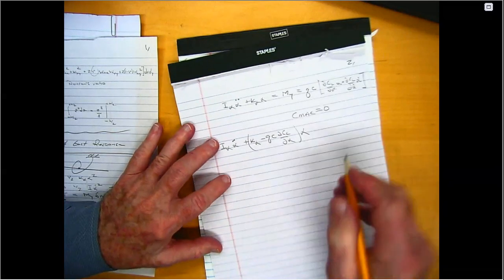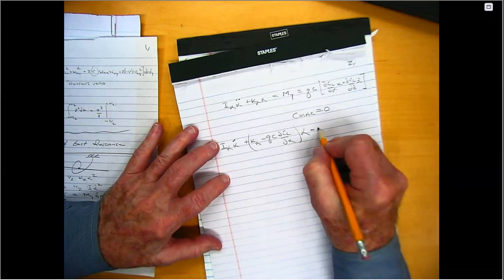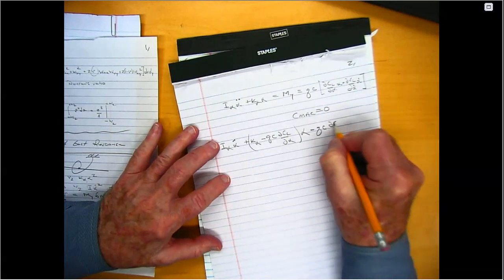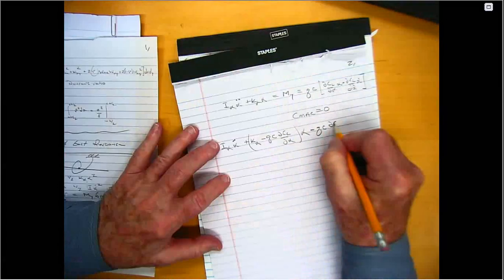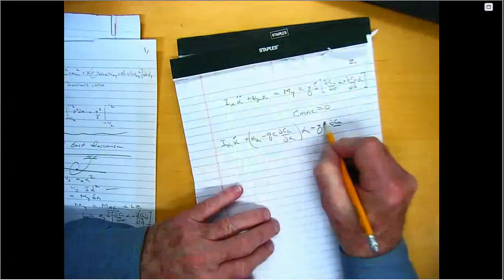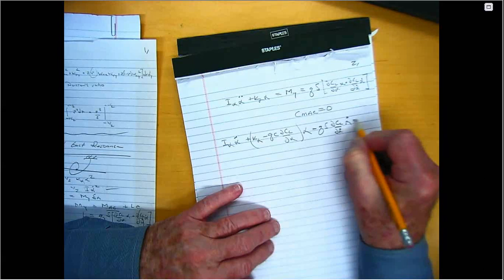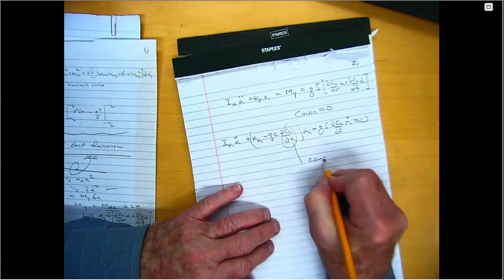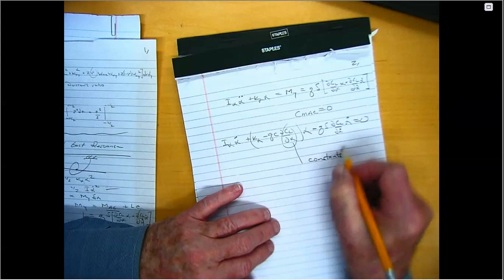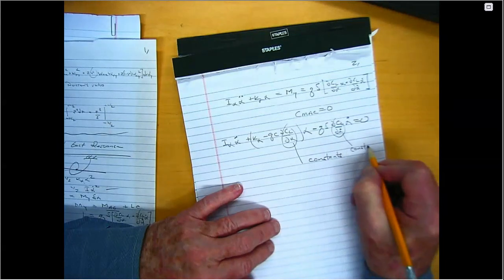And then minus Q C dC_L/d alpha dot times alpha dot equals 0. Excuse me, I've been saying C, I really should have put area here, so to be consistent with my notation, it should be S. Now these things are constants, at least for a linear theory, and I need some aerodynamicists to tell me what they are.